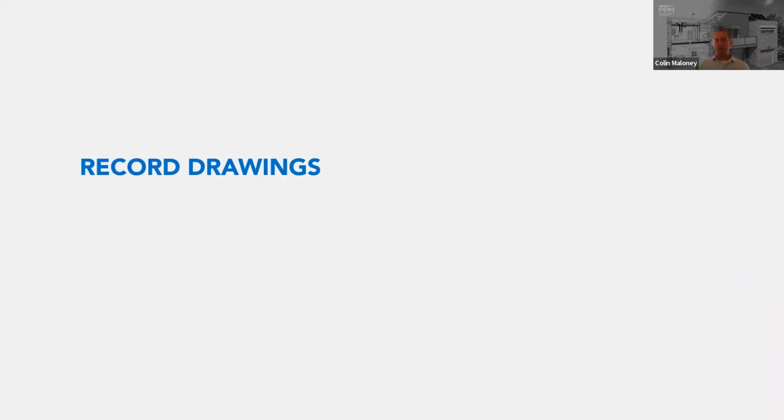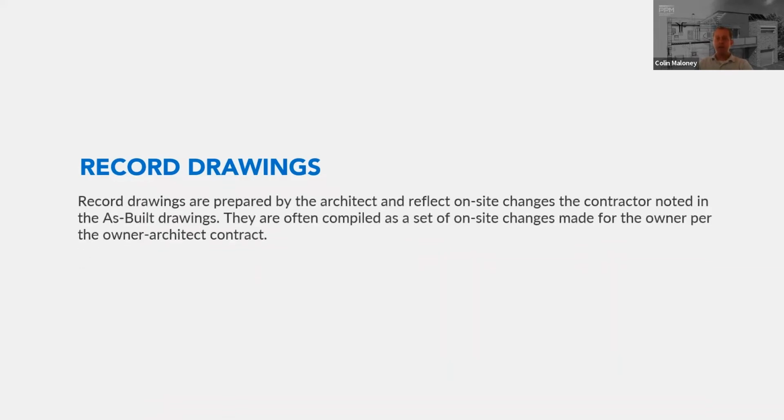Contractor-developed as-builts should not be confused with record drawings, created, of course, by the architect or engineer. Record or archive drawings often include the information gathered on as-builts and are the final set of formally developed prints, fully signed and stamped by the project engineer. This definition reads, this set is not always mandatory and created, but in general, some formal architectural services create these as one of the last tasks of a building project. And of course, everyone here takes the time to do that every time, right?